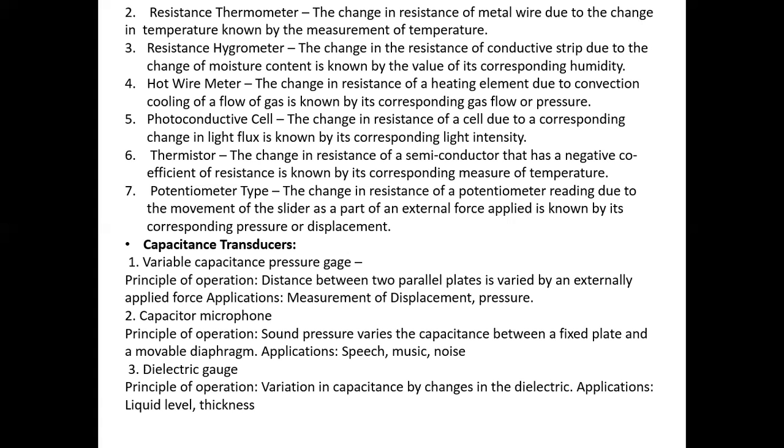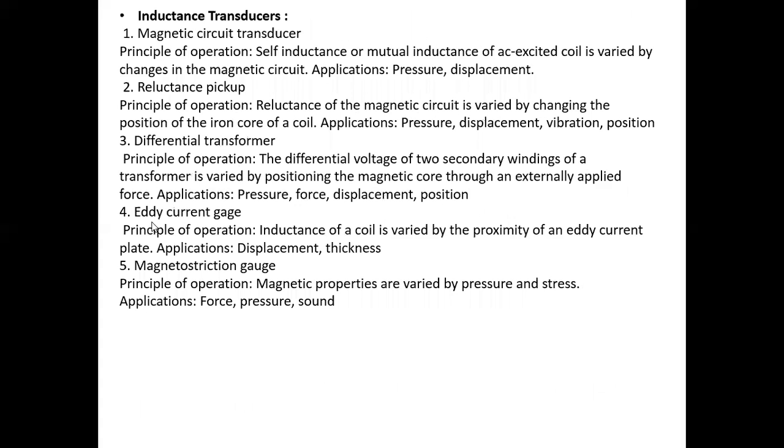Dielectric gauge operates on the principle of variation in capacitance by changes in the dielectric. Means as the dielectric material changes, the value of the capacitance changes, and it is used for the measurement of liquid level and thickness. The last topic is the inductance transducer.